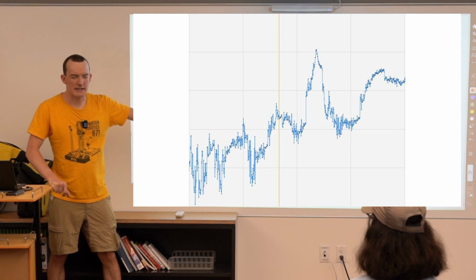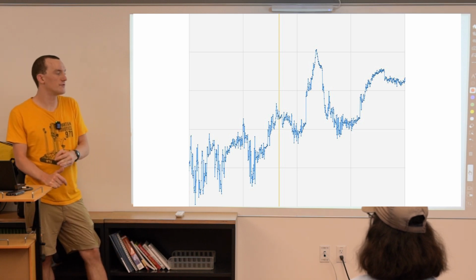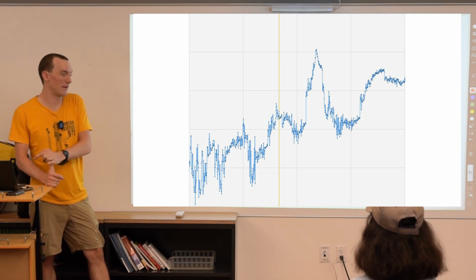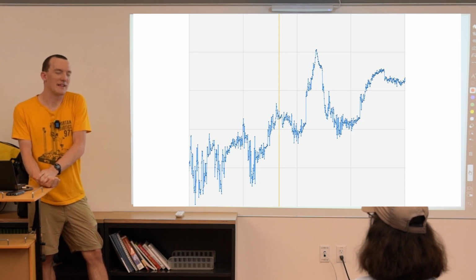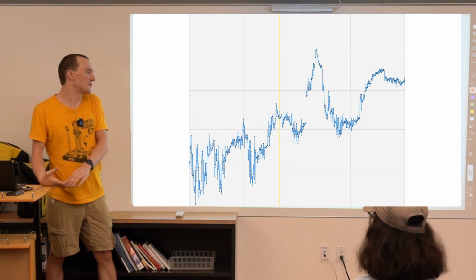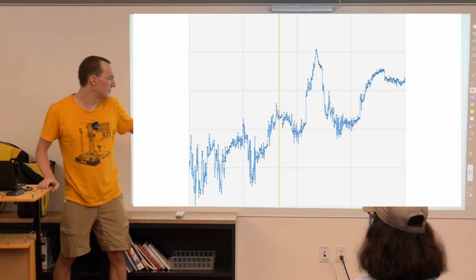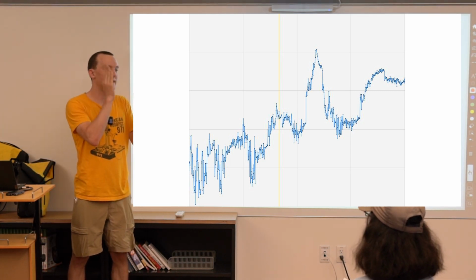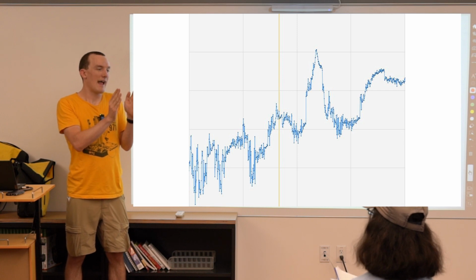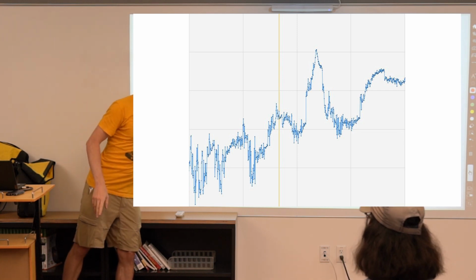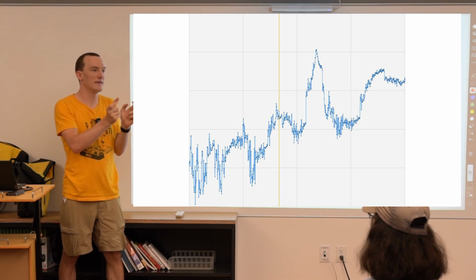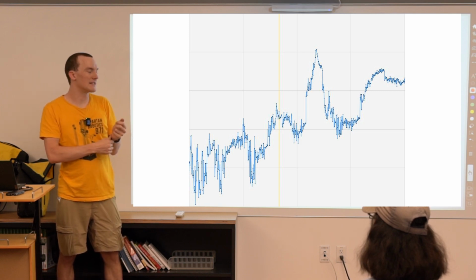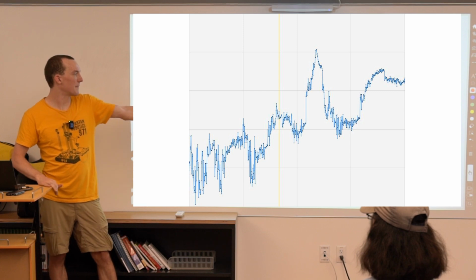There's a few different reasons this can happen. One of the reasons is that, like what I was mentioning, an encoder cannot directly measure the actual position it is at. It is measuring the number of counts it got. And so if you sample the encoder at two points in time, the way that you would typically get this sort of direct number is you take the difference in those two samples, you divide by the difference in time at which the samples are taken, and you put that up here.